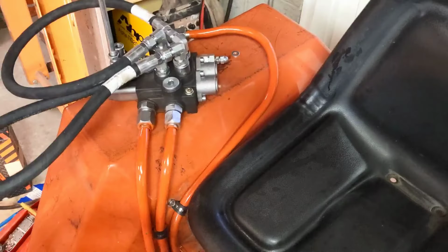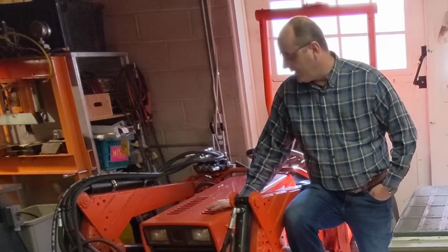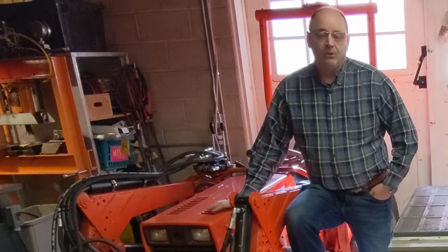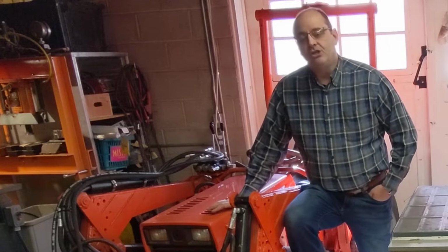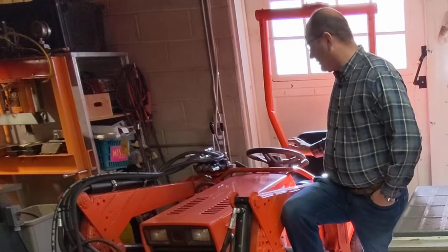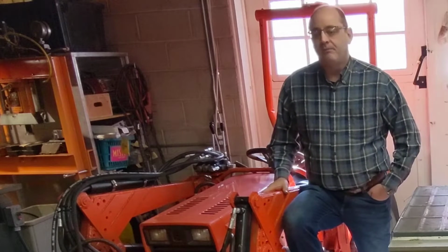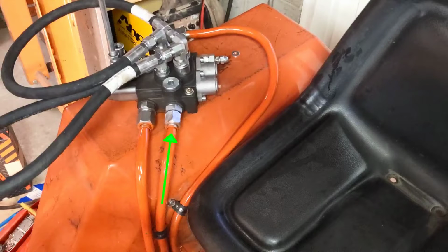Now, this tractor came from the factory with steel hard lines made from steel hydraulic tubing, flared on both ends, and connected with JIC hydraulic fittings. So I created a new set of steel hard lines using the same kind of tubing and flaring and fittings, and diverted my main pressure stream from the pump up to the new control valve, and from that control valve's power beyond down into the factory travel control valve.